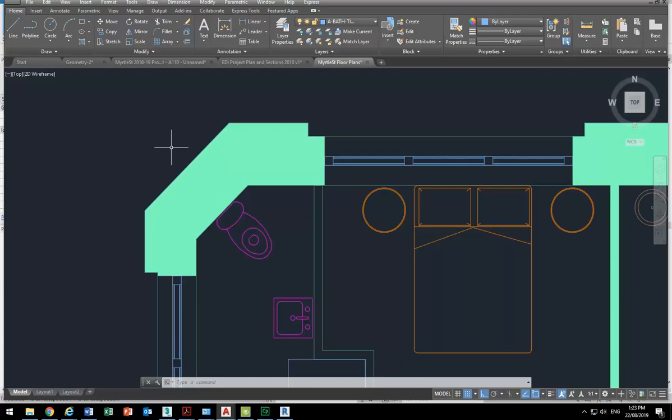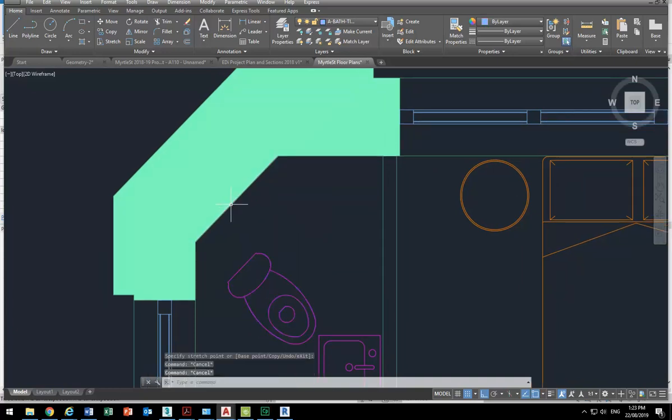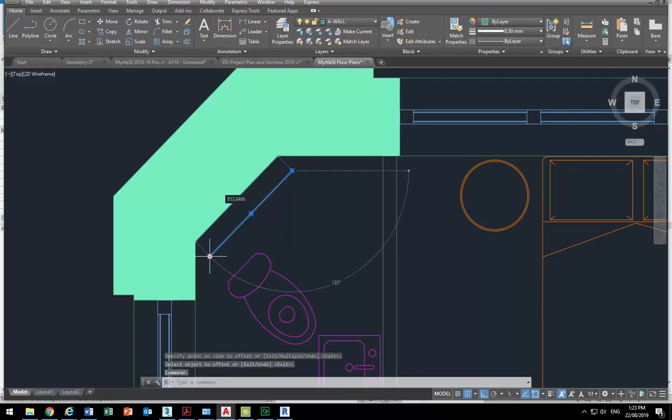So you've got to allow space for a pipe like that, and then also remember there are probably going to be other services like water supply that are going to go through that as well. So then just allow that sort of space. Here maybe this toilet needs to come out a bit, and you can get some of it into the walls, but that means you've got to change the wall, and that might not always be possible. So if you instead build in a new duct, I'll offset 150 from there, and then I know I can frame that out and have room for the duct.